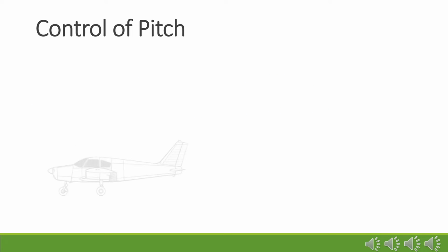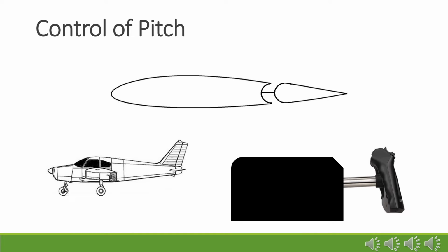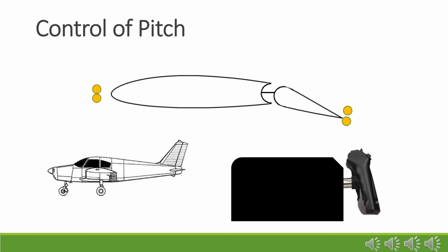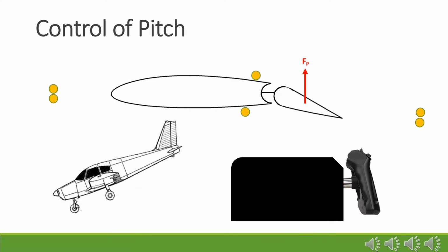Pitch control using the yoke is very similar to that of the joystick. With a control yoke at the neutral position, the elevators remain in the center position, there are no normal or perpendicular forces, and the drag force is minimized. The aircraft maintains a constant direction. By pushing the control yoke forward, the elevators are rotated in a downward direction. The normal, drag, and perpendicular forces are applied, with the perpendicular force pushing the tail upward. This upward push on the tail of the aircraft causes the nose of the aircraft to rotate downward, and the aircraft descends.